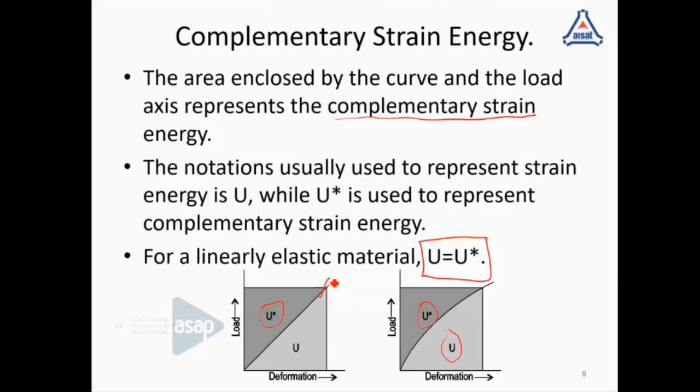When you are writing about the linearly elastic material, you should explain the strain energy, then complementary strain energy, and this relationship also you have to explain. So in all the cases, we will be considering the elastic region of deformation, and elastic strain energy is being considered in the following explanation.